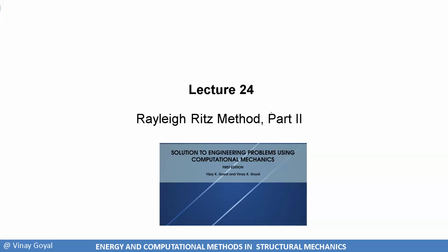And then I applied it to very specific problems like Castigliano's theorem, which is actually also based on calculus of variations. The benefit there is that we can now solve for particular deflections at particular locations. Maybe you cannot get the full field solution for the whole problem, but you can find the deflections at particular points in the system in a very simple way, just by calculating the strain energy.